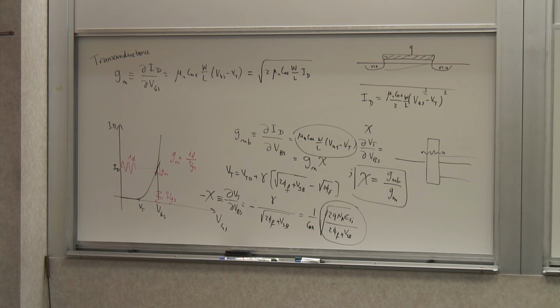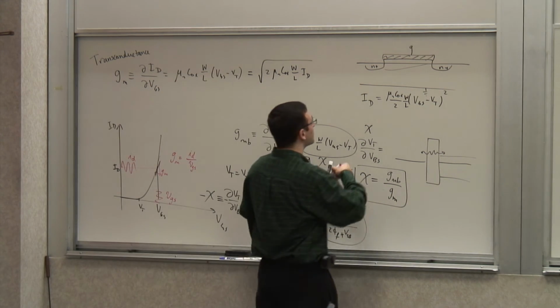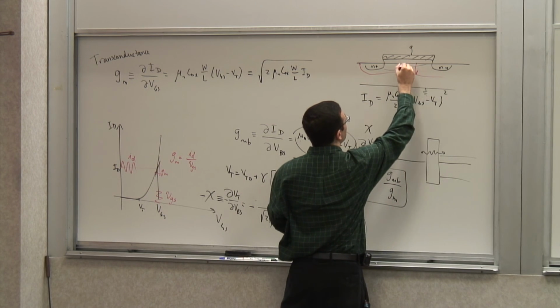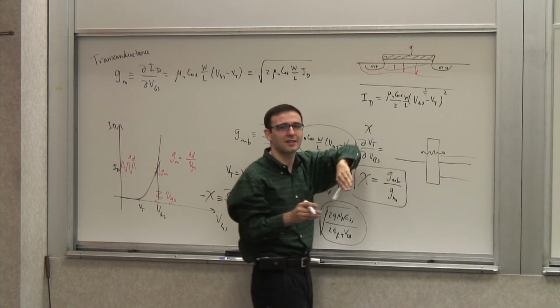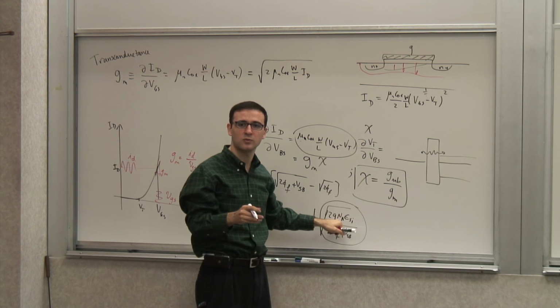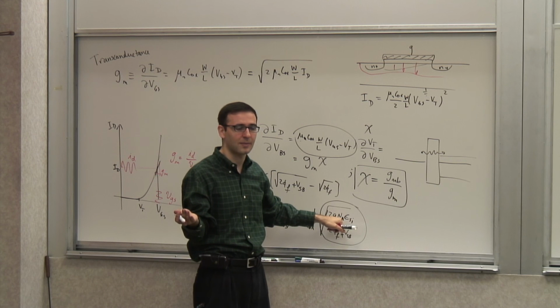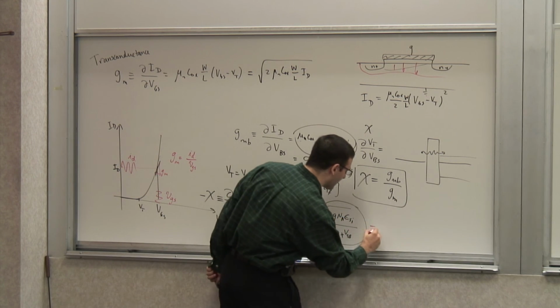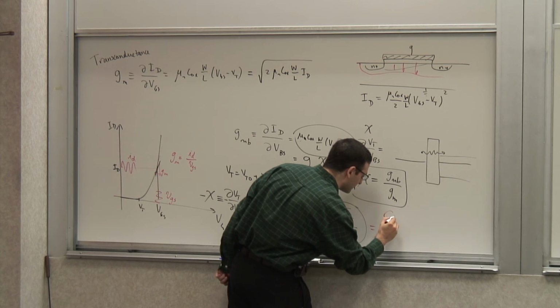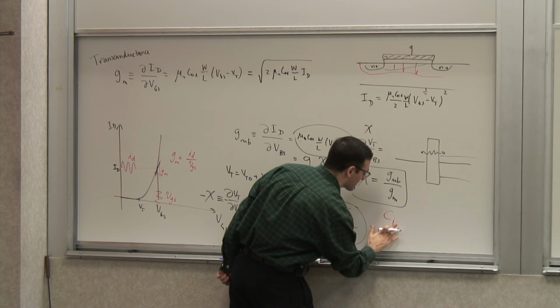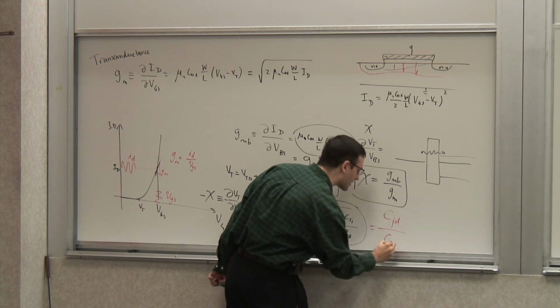Kind of a capacitance. It's not, is it? The depletion capacitance. You remember the expression we had for the capacitance of the depletion region? This is actually the capacitance of this depletion region. Well, it's at one side of capacitance. That's why you don't have the ND. It was 1 over NA plus 1 over ND, but you don't have the other side of it. You just have only one side of the capacitance. So it's nothing but the CJ, or let's call it CJD for the depletion capacitance, divided by Cox.